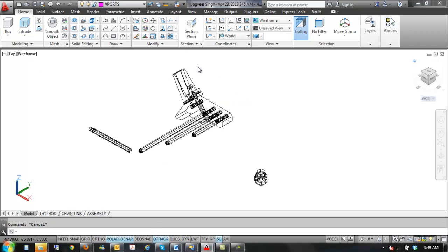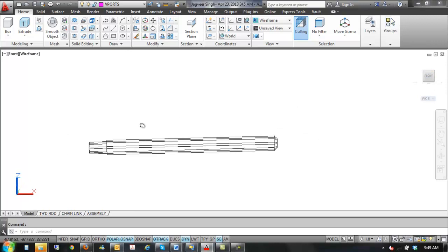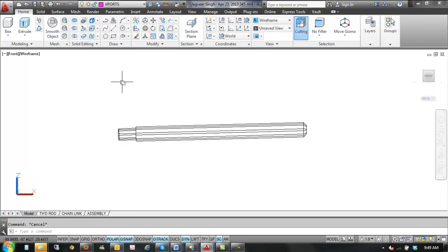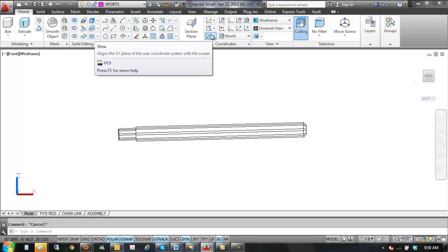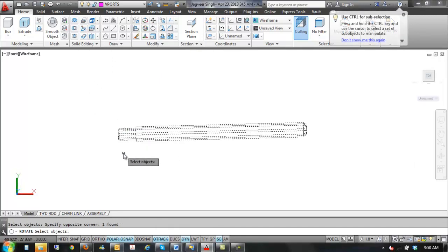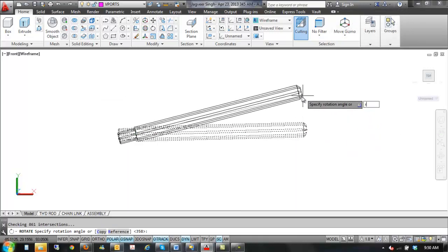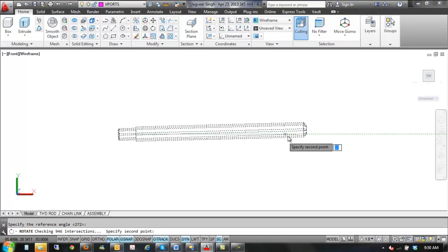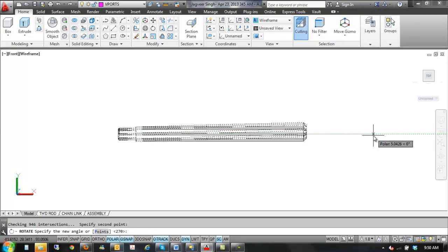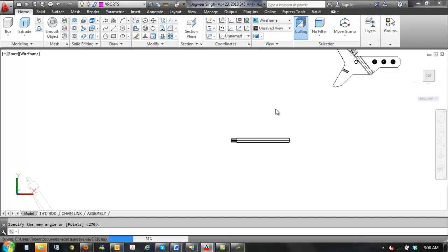Then go back to here and we'll look at the front view. Oh, it doesn't look like it's straight there, does it? So we'll straighten it out there at the same time. So Z and X is down here in the corner. So I'm just going to flip this to view, and then I can use the 2D rotate and grab a center and R for reference. So center and another center, and then line up with the polar. So now I'm squared up in all the different axes.